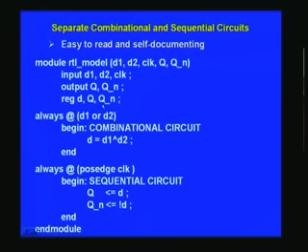So some sort of storing is taking place there. In general, whatever is an output defined in a particular always block, you declare as a reg as a general rule. Here, d was an intermediate output, which is nothing but the exclusive OR of two inputs, so you declare this d as a reg, and that is what we have done. And naturally q and q_n are reg, being the D flip flop outputs.